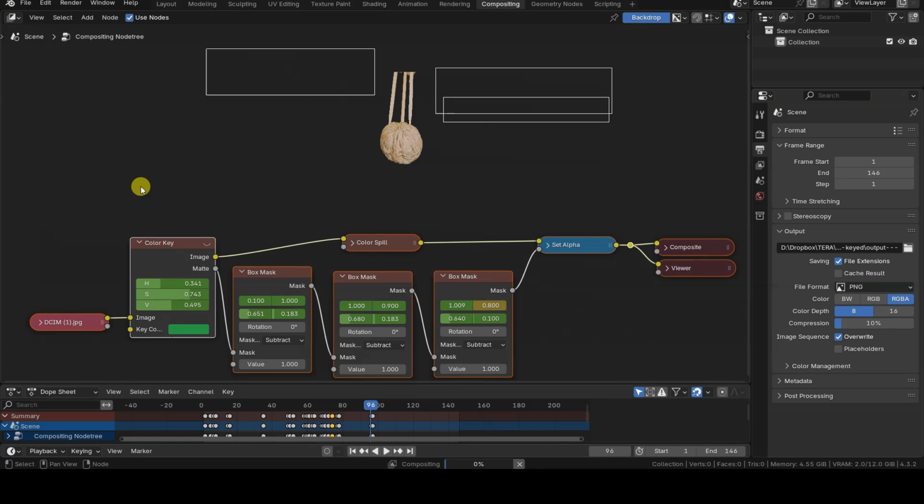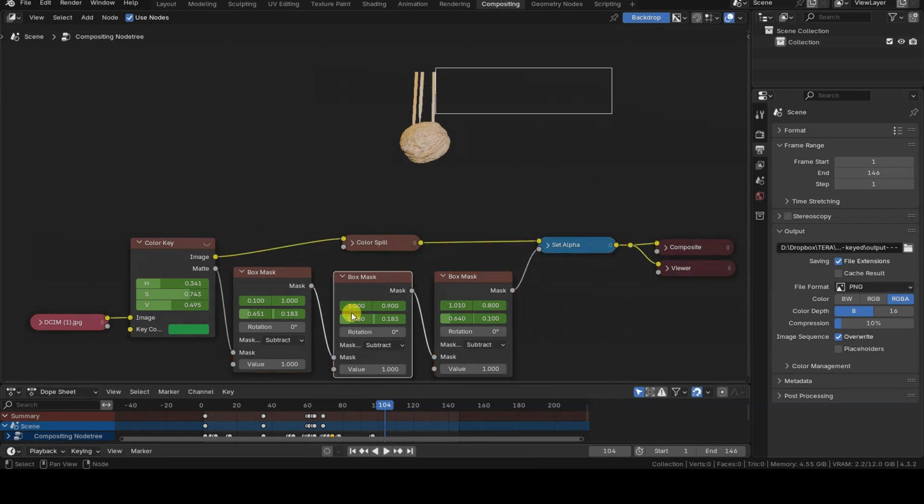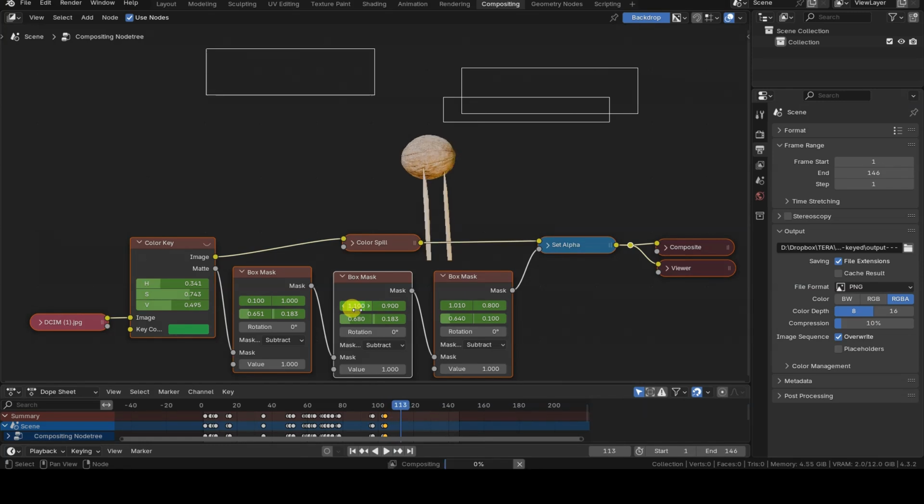This process of analyzing and adjusting the color key values and masks may take some time, but will save a lot more time later when Meshroom processes these cleaned up images instead of the original ones. However, it is not a big issue if you cannot remove every single unwanted element, as Meshroom will still interpret some small artifacts as noise and automatically ignore them. The more we can refine at this stage, the better, but there's no need to overcomplicate things.